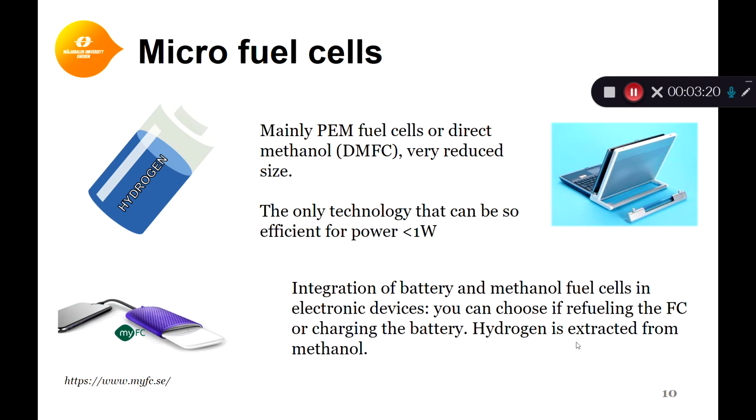So it has been suggested to use fuel cells instead of batteries, with the advantage of no need for electricity to recharge; they just need the fuel to be stored. PEM fuel cells have found some application in this field, together with direct methanol fuel cells, which are fuel cells that can use liquid methanol directly as a fuel.